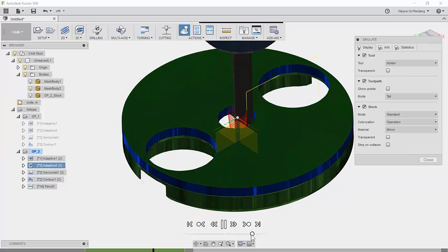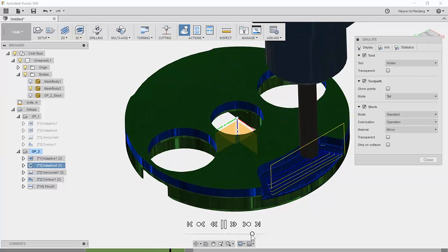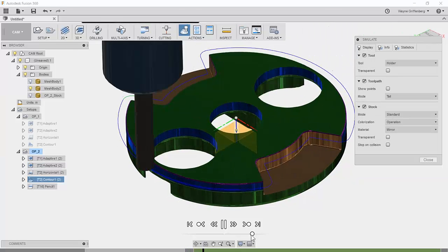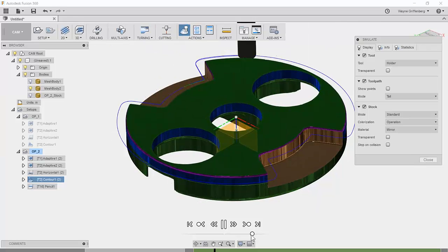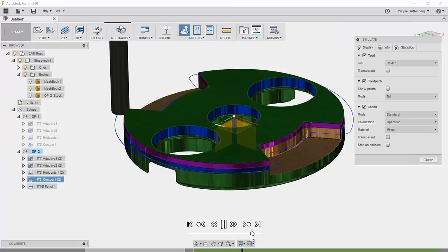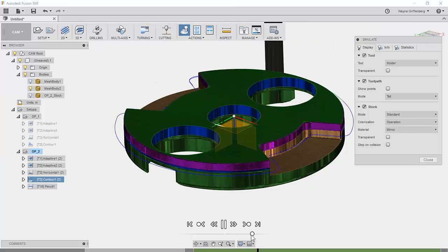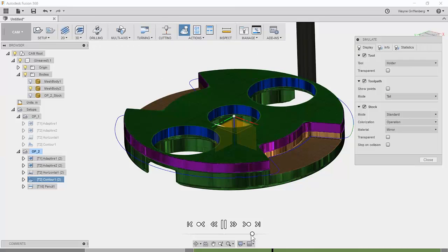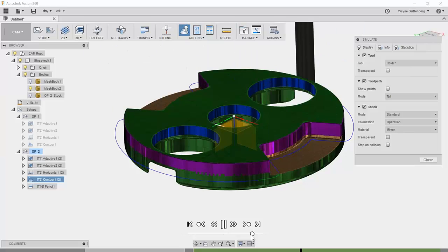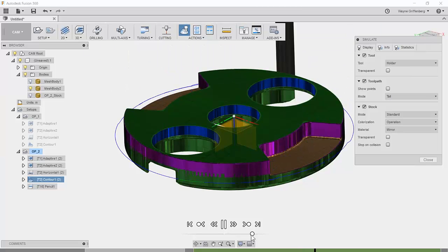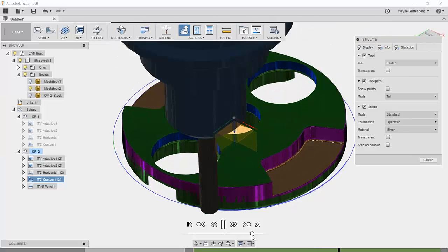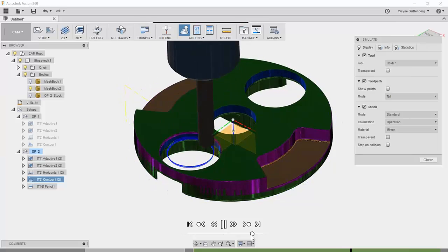I see a question about soft jaws. I'm thinking where you're headed with that is wanting to actually create the soft jaws, and that is a little bit more problematic just because it is an STL file, it's not geometry. It doesn't mean you can't do it, you just need to take into account that you're working with an STL file. And again, Wayne, I think you might have had some resources that you could share on how you can help convert that into a solid. But it's not the complete level of accuracy as a parametric solid that was drawn natively in Fusion.